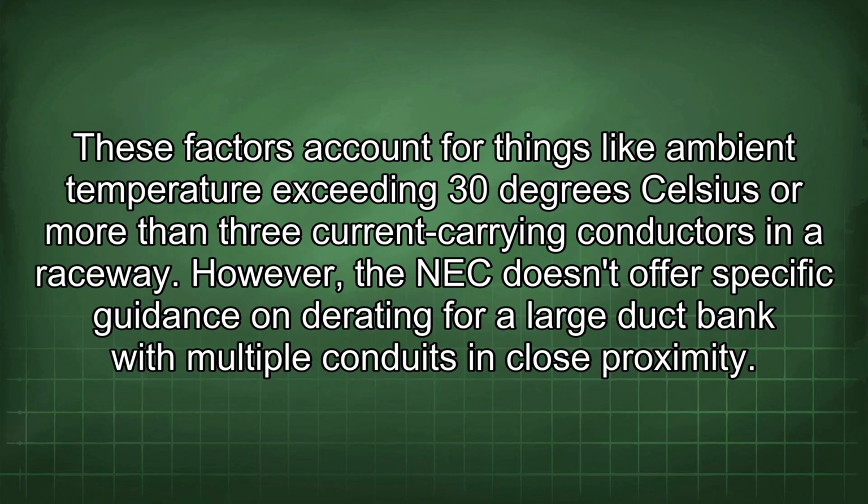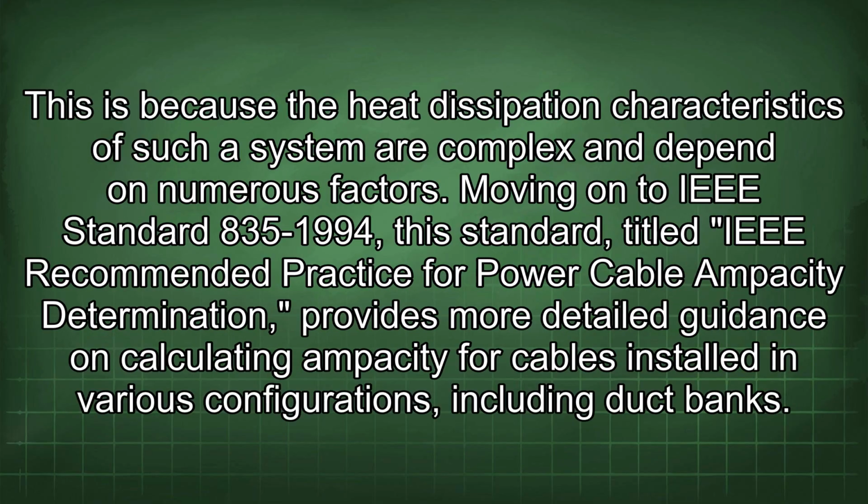These factors account for things like ambient temperature exceeding 30 degrees Celsius or more than 3 current carrying conductors in a raceway. However, the NEC doesn't offer specific guidance on rating for a large duct bank with multiple conduits in close proximity. This is because the heat dissipation characteristics of such a system are complex and depend on numerous factors.